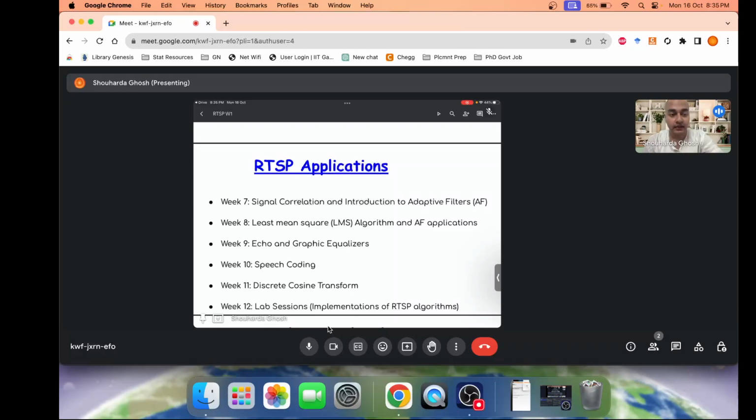But then you take blocks of 8 by 8, in general based on JPEG, and then do all kinds of processing. For example, you encode the image, then you do a prediction of the image and send the difference between the predicted and the actual pixel value. On the DCT components, an important point was that human vision is much less sensitive to high frequency coefficients and more sensitive to low frequency components.